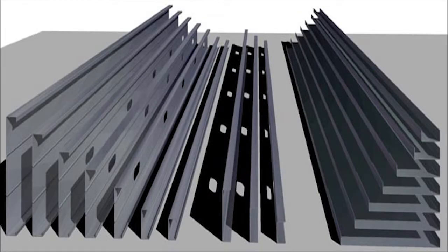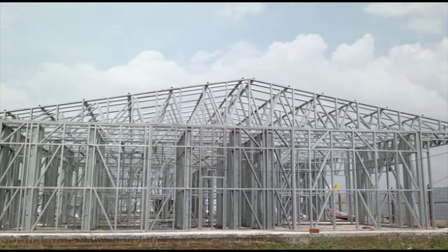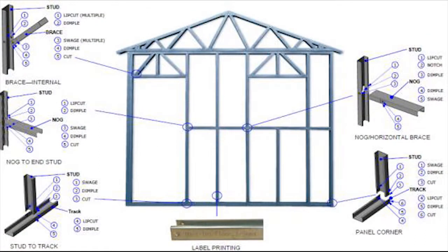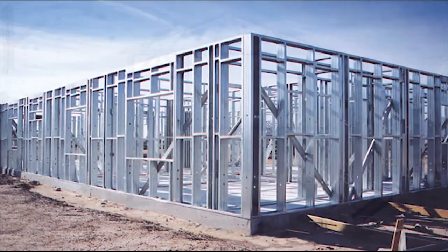Since light gauge steel is a very light material, which resembles timber structures, it is a good solution for a shelter following an earthquake, because lighter weight structures are less likely to cause fatalities than collapsing masonry structures in future earthquakes. On the other hand, though, light gauge steel is probably not the best solution for a post-hurricane location, since it is more vulnerable to strong winds.